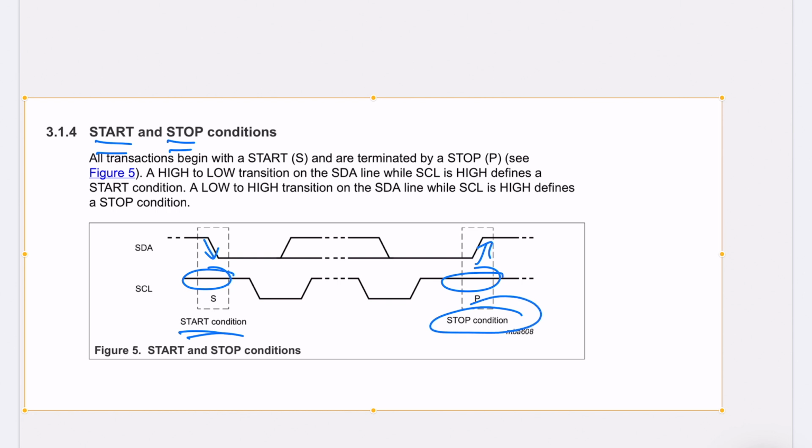This is very important. Sink it into your head, whatever you need to do, rewatch this. As data is dropping while the clock is high, that's a start condition, and as data is rising while the clock is high, that's a stop condition.